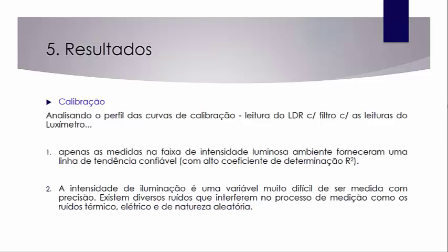As for the thermal noise, we can talk about the temperature that increases the number of free electrons and the conductivity, decreasing the resistance of the LDR. Noises of this nature can be reduced by taking measurements in a controlled environment and preferably at low temperatures. Random nature noises come from variations in the natural lighting environment and from the movement of persons in the measurement environment, causing shadows on the sensor.